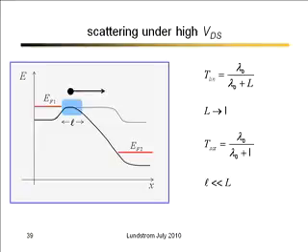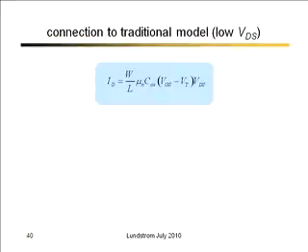Right? You have the same mean free path because you're still under low field, near equilibrium there. That hasn't changed. The mean free path is much shorter here where the carriers are very energetic, but it really doesn't matter as much there. So this is the explanation. The total amount of scattering in the transistor does increase, but the probability of getting across the bottleneck region is increased. All right.